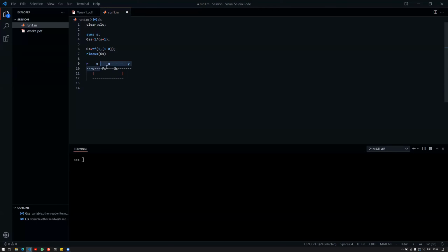So we try to come up with a controller that makes this error stable, or in other words, it forces this error to become 0. If that's the case, then we have a control signal, we apply that to the system, and then we observe the output. The simplest controller, in my mind, would be basically U equals E. So 1 times E, because there's not even a gain. The error is directly fed to the system as an input, but this might not always work.